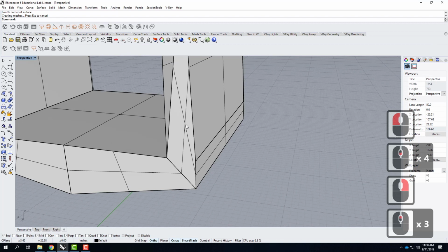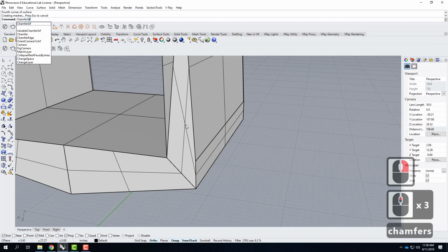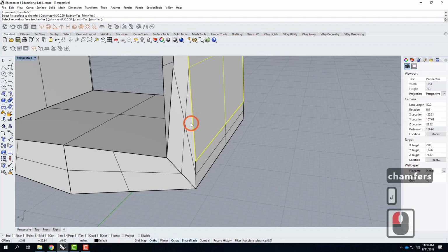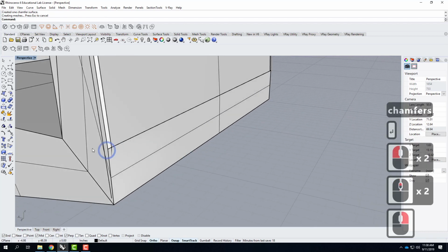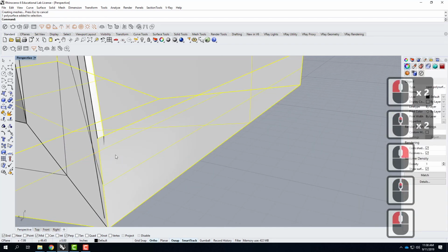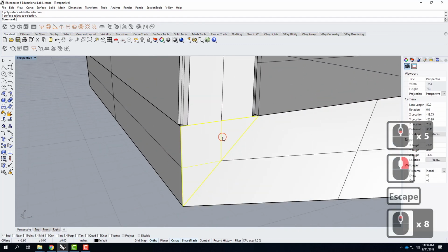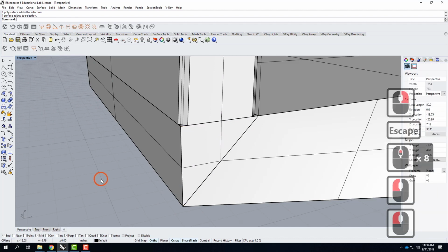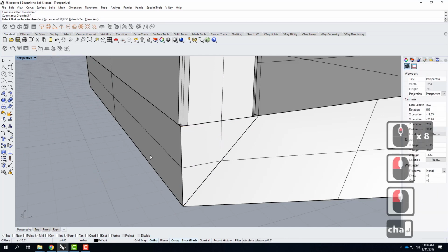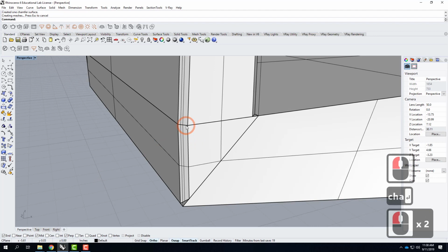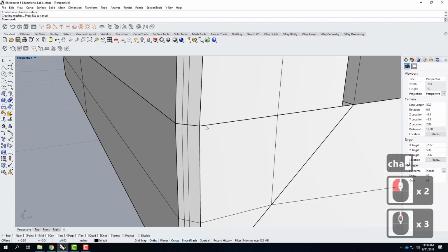When I go to chamfer these two pieces, there to there, I'm going to get really funky results down here because I have different surfaces trying to chamfer. It's not clean. So instead, I went ahead and I created this as a separate little surface, which will allow me to use the chamfer surface command to take this and put those together and see how that corner meets really nice and clean.